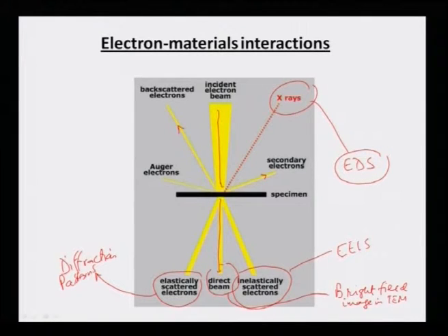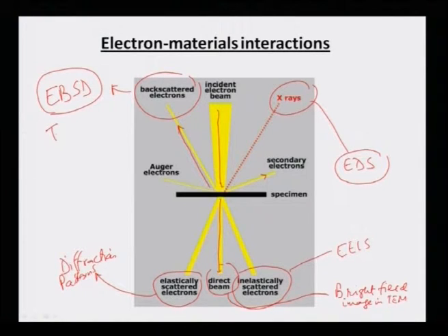What I have not talked about is that the backscatter electron can also be used to obtain crystallographic information in SEM. There is a new technique which has been developed of late, from the 1990s, known as electron backscatter diffraction or EBSD, that is used extensively now to get diffraction information as well as texture studies in the material.